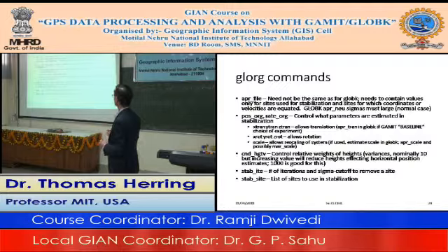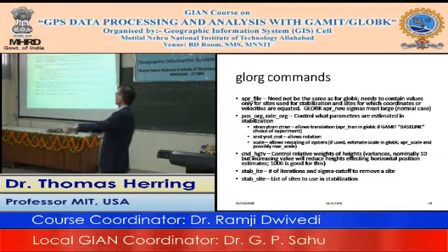This allows for translation. When you do this, you should turn on the APR tran command in GLOBK in the baseline, if you ran GAMIT in the baseline mode, which is what we normally do. XROT, YROT, ZROT allows rotation, and again, you should have on the APR WOB and APR UT1 commands when you use that. And then scale allows for rescaling of the system, and again, you should have APR scale turned on when you do that. So these tell GLOBK how you want to reorient your frame.